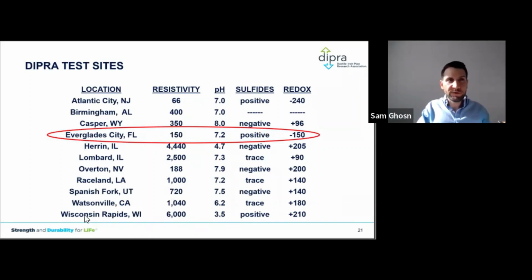Those soils are very common. We see a lot of those in Canada, but in the prairies, for example, and in some parts of Ontario, you have aggressive soils, also called hot soils, which could be close to 500 to 800 ohm centimeter. Okay, this is a uniquely severe environment at 150 ohm centimeter, where any metal you bury in that ground will be gone in a few decades.